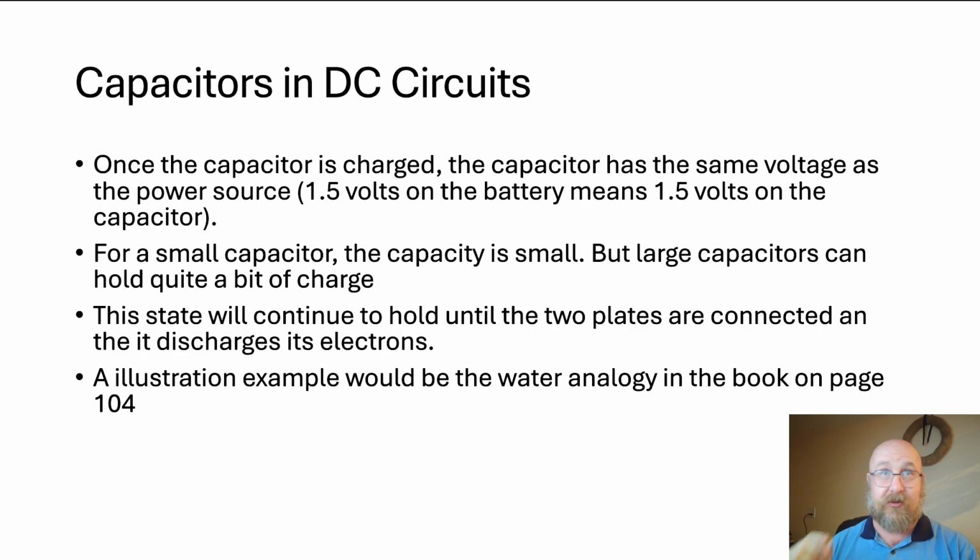So don't grab any capacitor, but particularly a large one, with both hands, because you'll shock yourself. It's always a good idea to discharge them in a safe manner by either touching the two leads together to discharge them, or using a metal bar that you're insulated from, like perhaps a screwdriver, to touch those and make sure that it's discharged before you work with that capacitor.